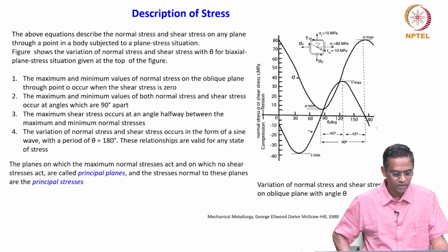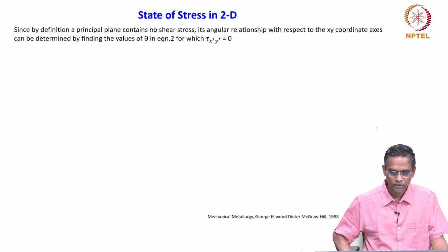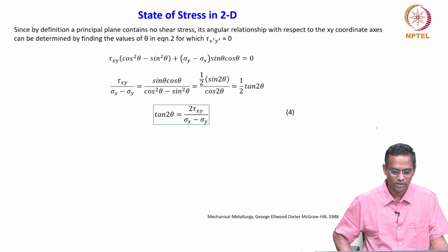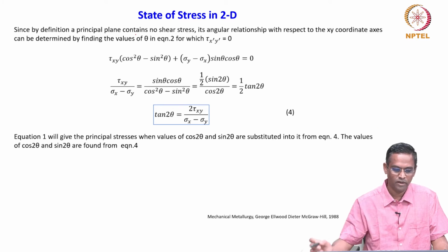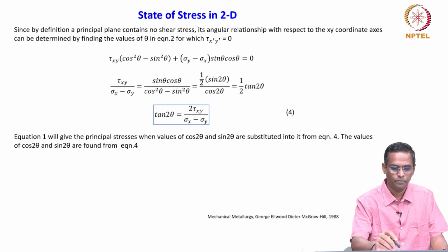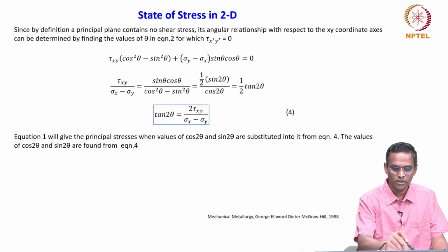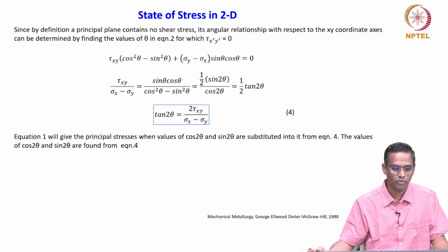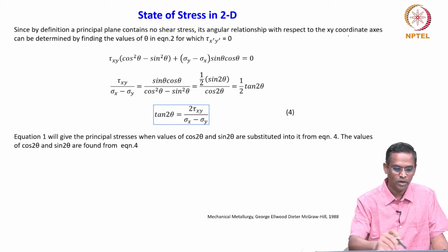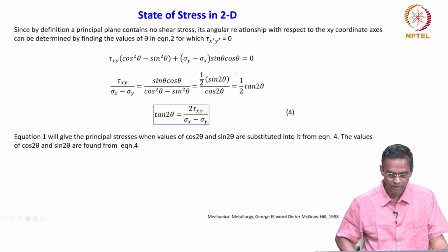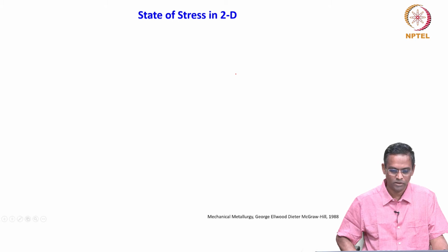So we discussed that, and we were trying to calculate the principal planes from these equations. Where the principal stress is acting on a principal plane, there is no shear stress, and its angular relationship with respect to the xy coordinate axes can be found from the shear stress equation.